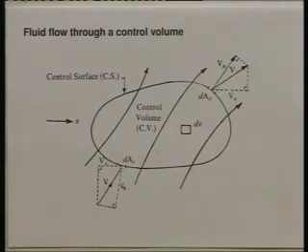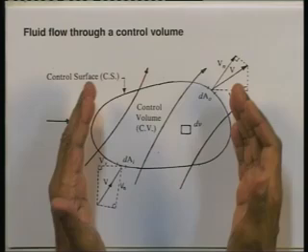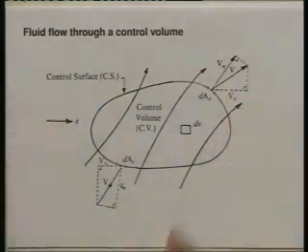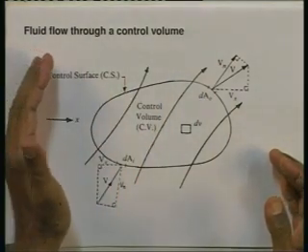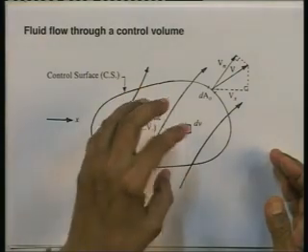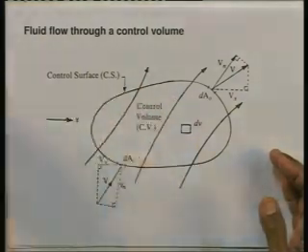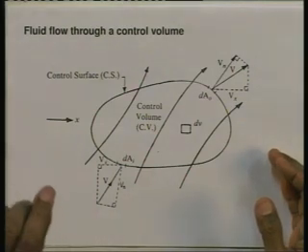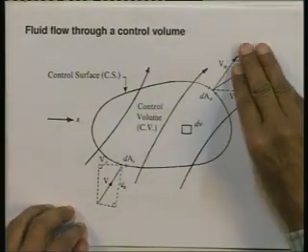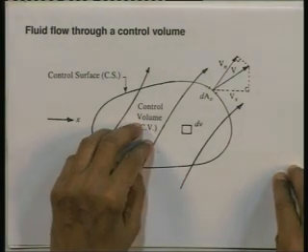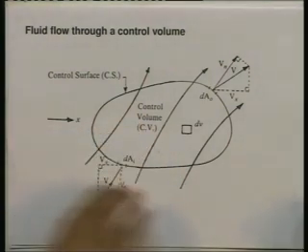All right. So, notice now the moment I go to a control volume approach, I have 2 extra terms. The first 2 terms, x direction forces acting and rate of change of x direction momentum inside the control volume, are the same as for a closed system, but the two extra terms come in because there is flow going in and there is flow going out. So, it is a plus the rate at which x direction momentum leaves, minus the rate at which x direction momentum enters the control volume. Now, that statement I have given you in words, let me now give that statement in symbols. What we would get would be the following.